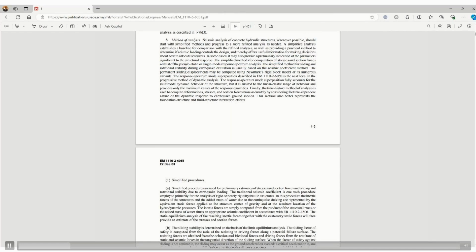See, we have carried out this pseudostatic analysis considering the seismic coefficient. The response spectrum is actually an enhancement of this pseudostatic method only. So in the response spectrum, we can plot the curve between the time period of any structure and the maximum response of that structure in terms of its acceleration, depending on its damping properties. Like for concrete, considering 5% damping, and the structural time period based on its shape, height, whatever, we can have the spectral acceleration of that.